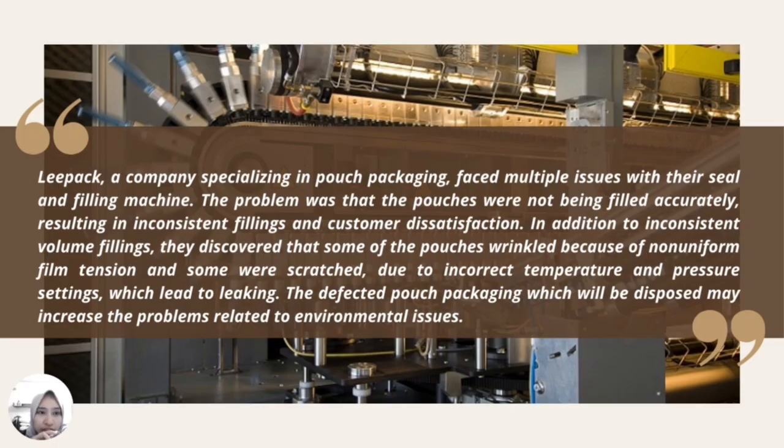Okay, so for the problem scenario, Lipack is a company specializing in pouch packaging. They face multiple issues with their seal and filling machine. The problem was that the pouches were not being filled accurately, resulting in inconsistent fillings and customer dissatisfaction. In addition to inconsistent volume fillings, they discovered that some of the pouches were wrinkled because of non-uniform film tension and some were scratched due to incorrect temperature and pressure settings, which led to leaking. The defective pouch packaging, which will be disposed of, may increase environmental problems.